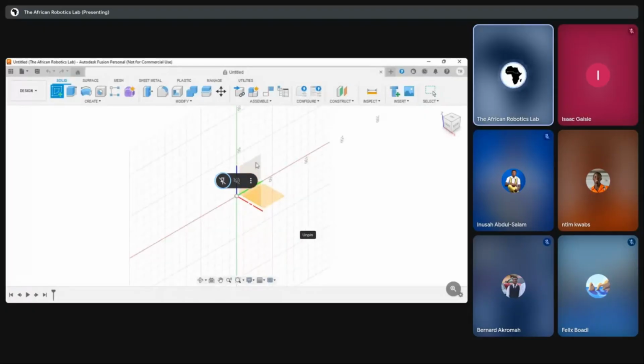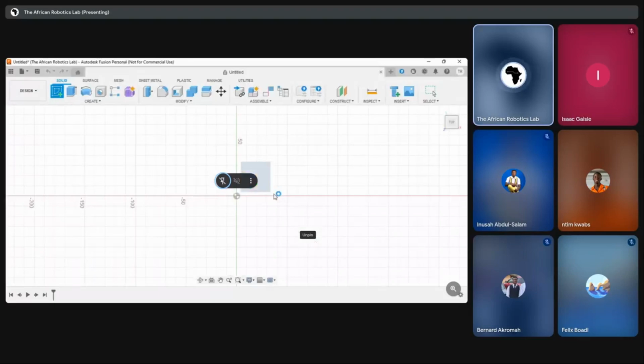If we want to create whatever sketch we want to create, we need to choose one of these planes, these axes, right? So there's a sheet of paper on a flat table. There's a sheet of paper that is in front of us, just like your computer screen. And then we have a sheet of paper that is on our left hand side, right? So that is basically it. But for our sketch, let's create our sketch on the XY plane, the paper on a flat table. Great. So we just click on that, and it's going to create the sketch on there.